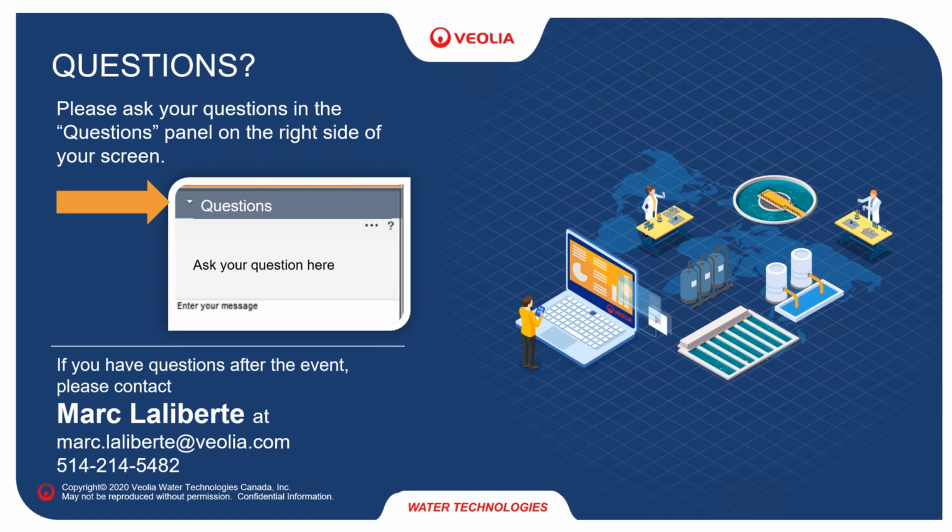If you need to remove that, you're probably looking at the combination of reverse osmosis with evaporation. Not sure how practical this is for a mobile treatment system. It can be done. Reverse osmosis, especially, we have wheeled units, but an evaporation system for a mobile treatment at a remediation site would be fairly complex to set up. But basically, if you're talking about soluble salts, nitrates, by the way, are the same thing. Nitrates, chlorides, some sulfates like magnesium and sodium sulfate as an example. All those salts cannot be precipitated.